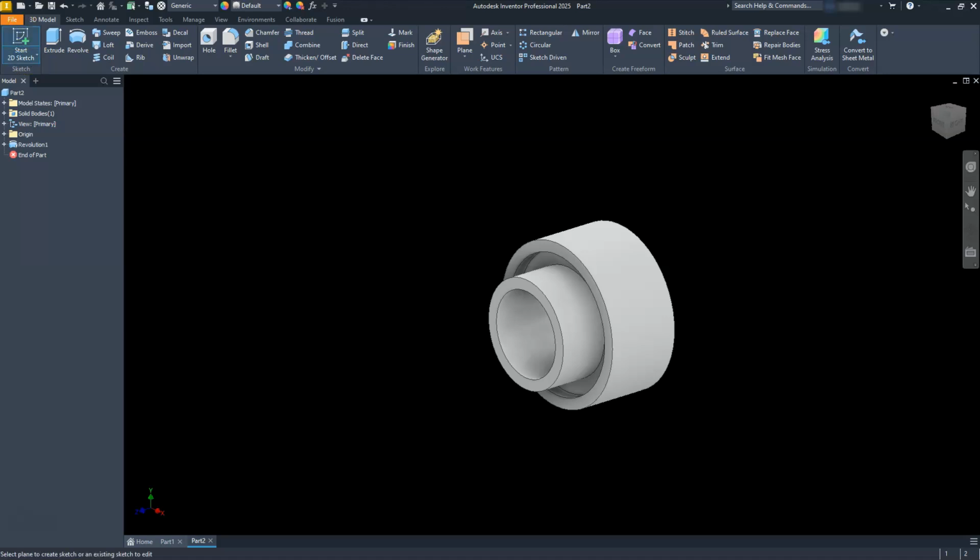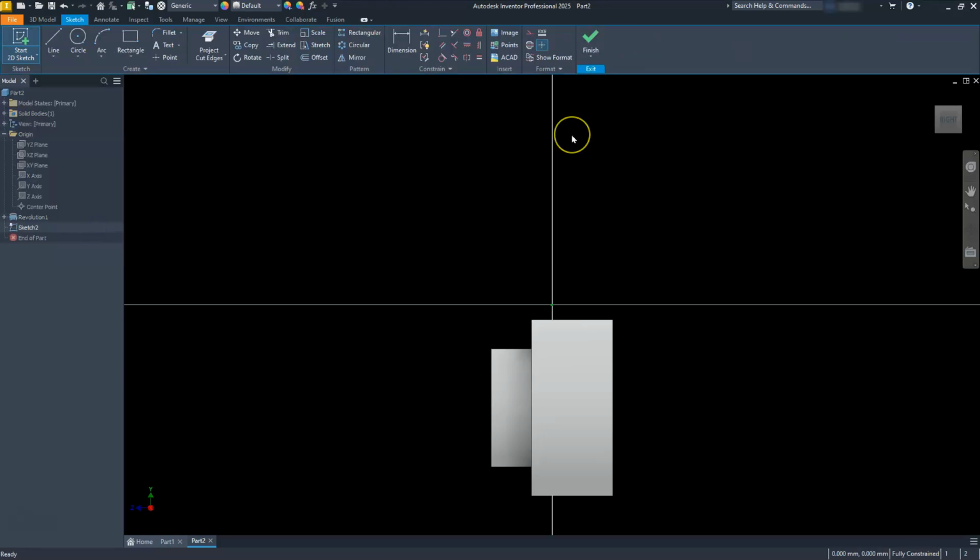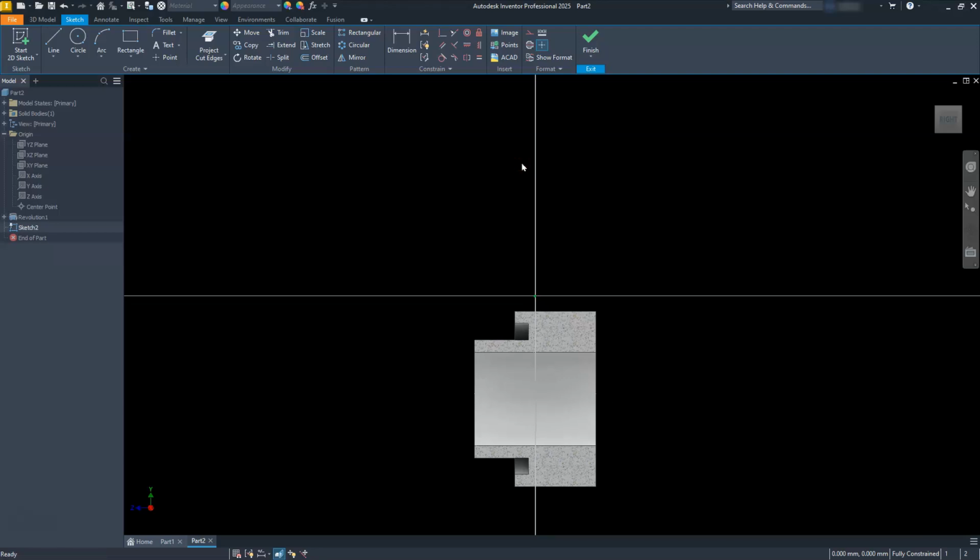So we're going to create a 2D sketch on the origin. And I said origin, I'm sorry, on the YZ plane there. So it's the exact same thing we did before. Let's go ahead and use the slice geometry here. Now I did tell you in the beginning that I was going to center or line this thing up, and I accidentally made it to the center. But I can go back and adjust that, and that's what I'll do here in a little bit. So don't worry, I made a mistake, but it's an easy fix in this program.